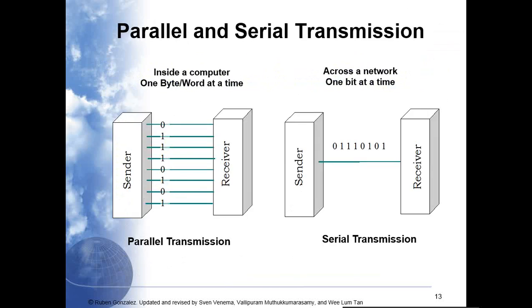So depending on how you've configured it, you'll need to make sure that that's processed in that particular way. Looking at the different ways to transmit data, you can transmit in parallel or in serial. In parallel, inside the computer, there's typically a line for every bit. Between two registers, all 8 bits are transmitted in one time unit. Is that feasible outside the computer? Not really. So we have serial transmission on the outside, where you send a bit at a time. You send them really fast, one after another, and then you have to grab them one after another on the other end.